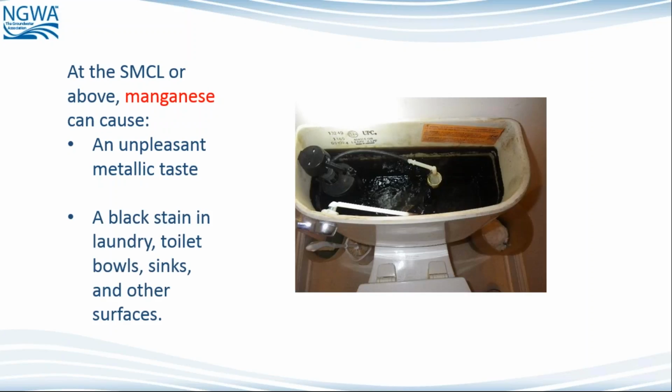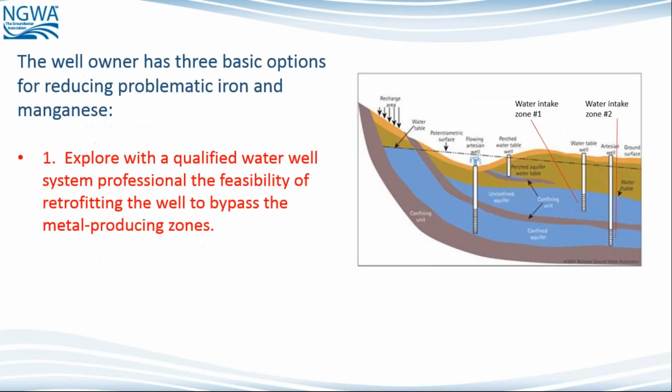As you can see, the stain of manganese is black. We would again find it anywhere in the toilets or the sinks where manganese water would have a tendency to stay. In our laboratory, when we have a sample that is dark gray or even black right off the bat, before we run any analysis, we realize that we're probably dealing with high manganese concentrations.